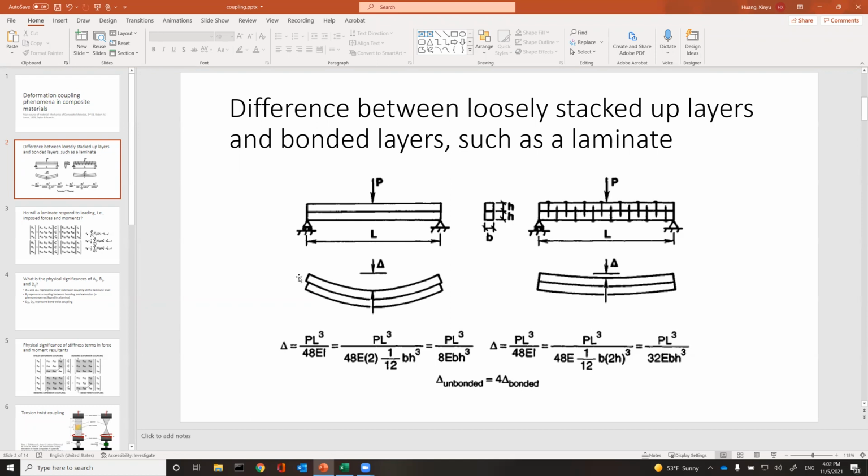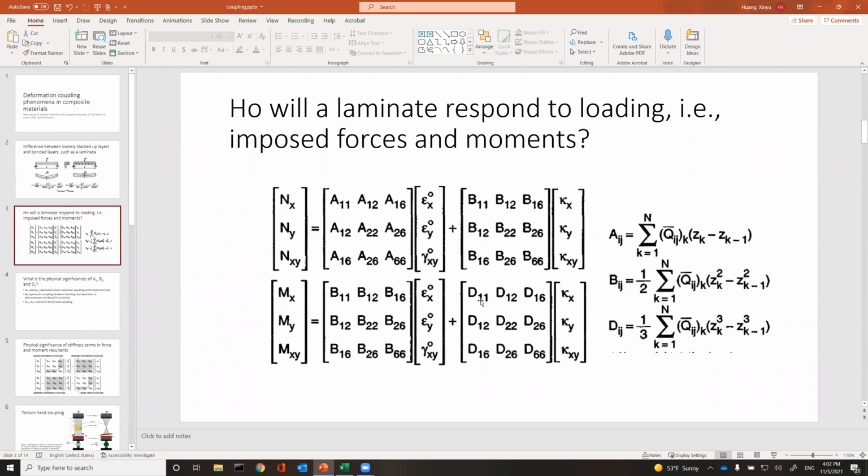All right, so the laminate that we have learned basically assumes all the layers are tightly bonded together. They're bonded together. They stay together. The interface is not separable, unless you overload it, unless you go over the failure threshold, and they debond and things like that. But before that happens, every layer is closely coupled together. They don't separate. They're one piece. And their phenomena are captured by this set of equations that we learned before.